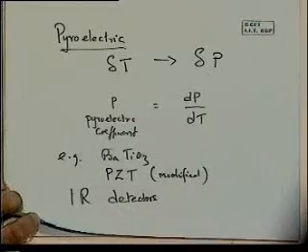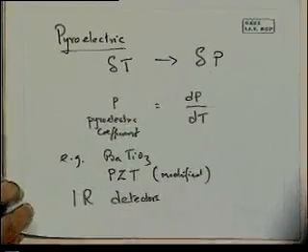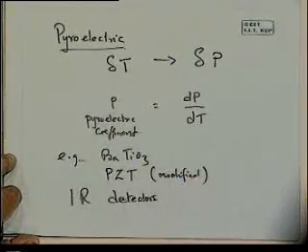The detectors can be made so sensitive that a change in temperature of even some few thousandths of a degree will generate a voltage because of the change in polarization that can be detected. So very minute temperature changes, satellite imaging, when you're going across, you can see how temperatures are different to detect whether it's vegetation or what, because temperatures are different. There are all kinds of applications. So the pyroelectric effect can be made use of as very efficient infrared detectors.